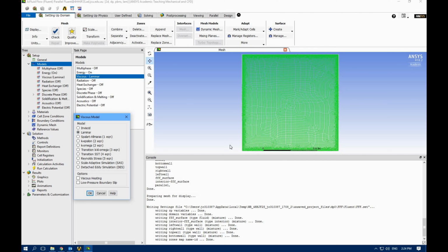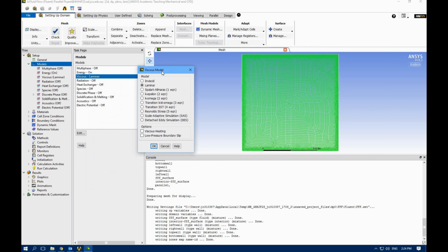You know what temperature difference you want to select. The working fluid is going to be air, so you can easily calculate the Rayleigh number. If it's under the critical Rayleigh number, you can consider it laminar. If it's above that, consider turbulent and select the turbulent flows. For simplicity, I'm just considering laminar flow.